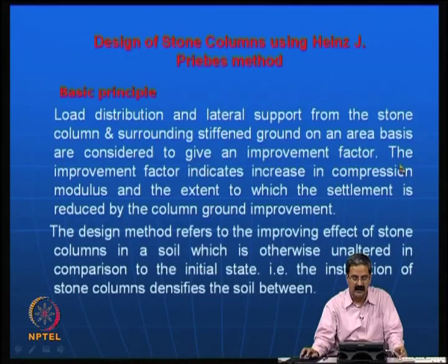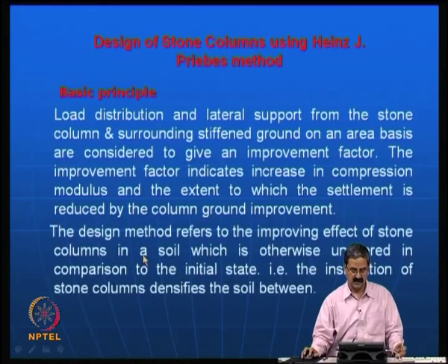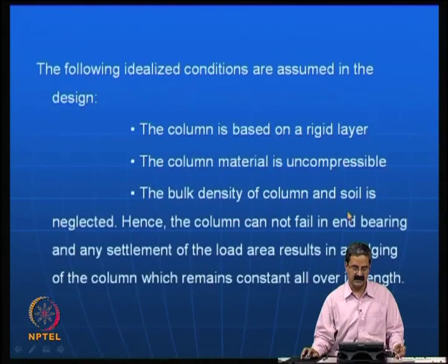So, this improvement factor sometimes can indicate the increase in compression modulus, like you can do a consolidation test where you get the compression modulus, and the extent to which the settlement is reduced by the column ground improvement. So, here in this design what we see is the improving effect of the stone columns in a soil which is otherwise unaltered, in comparison to the initial state, how the initial state has changed to the improved state.